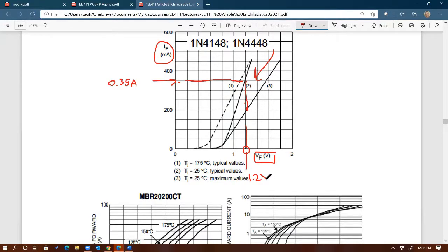That's pretty significant, isn't it? So this diode is very lossy, because when you have current and voltage together, they get married and have a child called power, which is V times I. So you can see the loss coming from this diode. Even at very tiny current, you get quite significant loss.